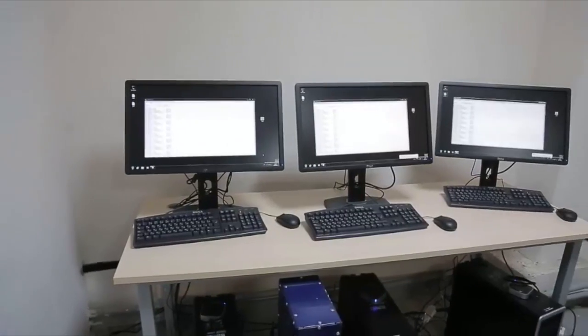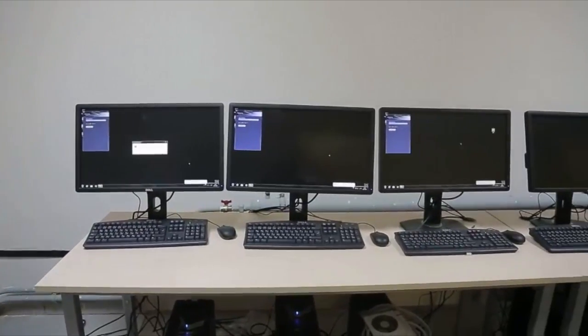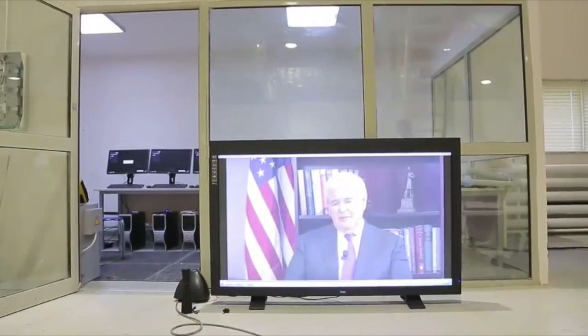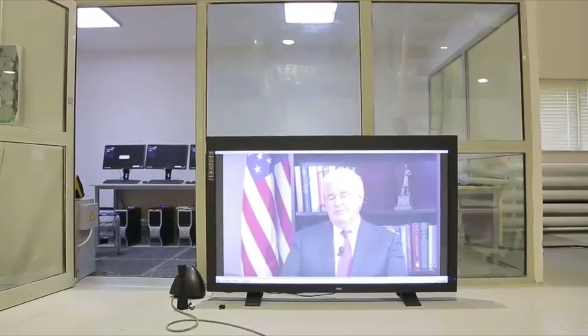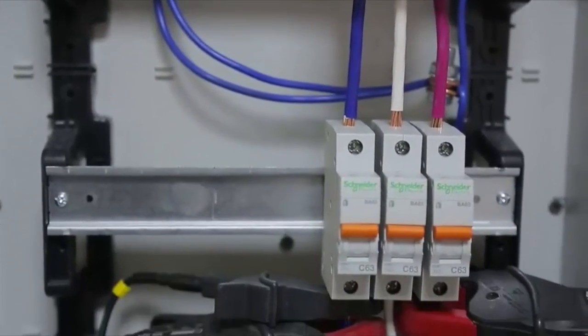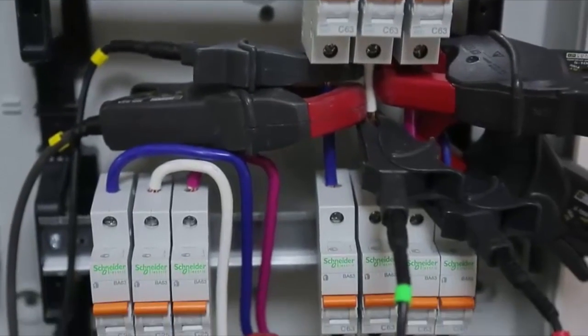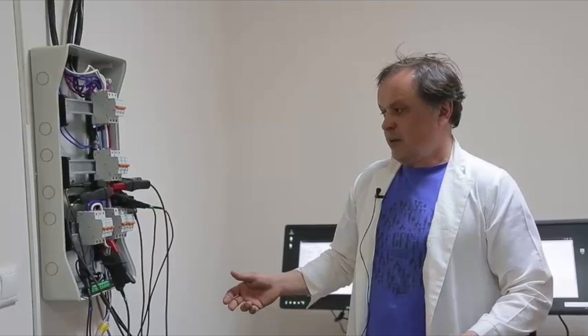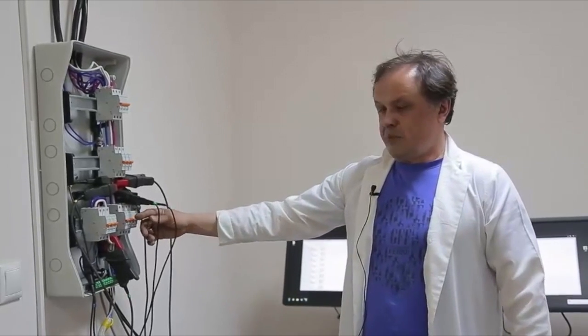Another know-how was tested on operation of a server or small data processing center. We are going to simulate failure conditions in the three-phase grid, specifically loss of neutral or any other phase. In addition to servers, we have a 150 cm plasma panel connected to the three-phase grid. As we know, in case of open circuit or short circuiting of neutral in the three-phase grid, the voltage of 220 volts will grow to 380 and by that cause failure of sensitive equipment.